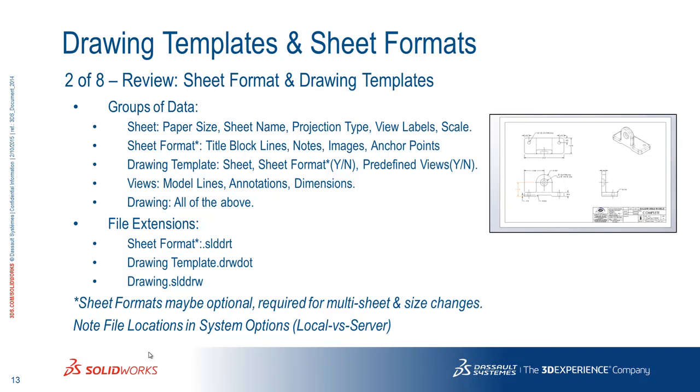And I've got a note to myself here: sheet formats may be optional. Some companies don't actually make these sheet formats at all, and you don't really need to. But if you're going to use a multi-sheet drawing, if you've got more than one page to a drawing, well, then you're going to need a sheet format.